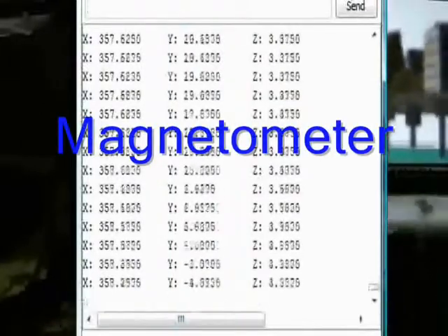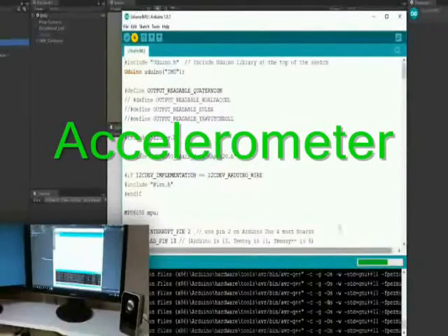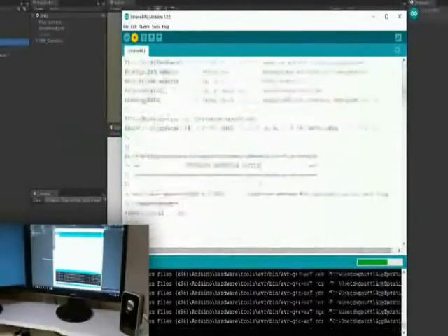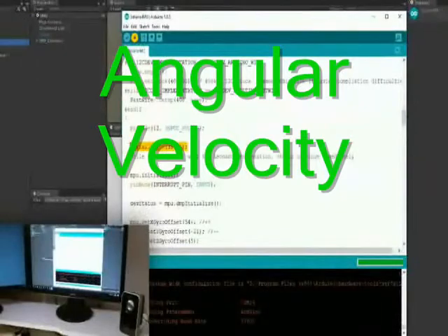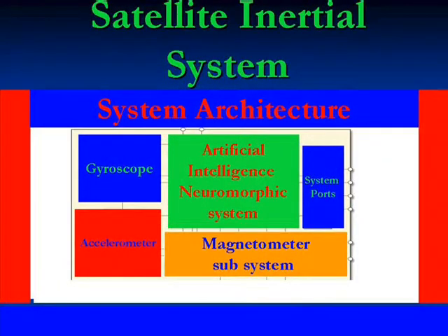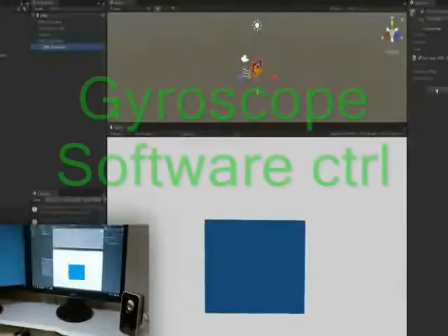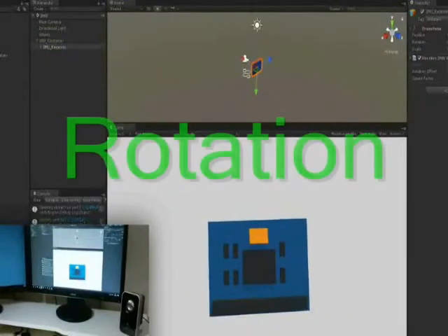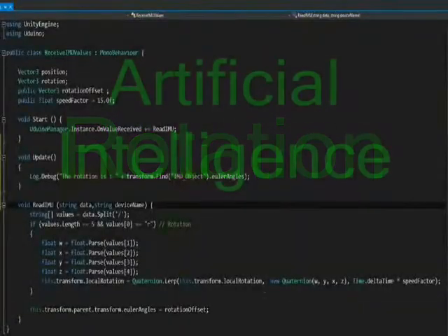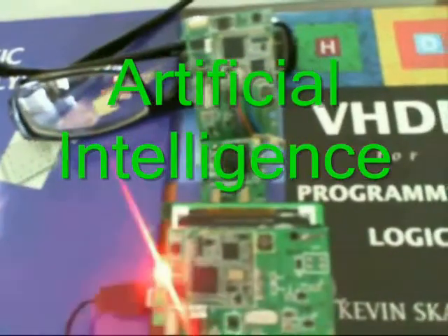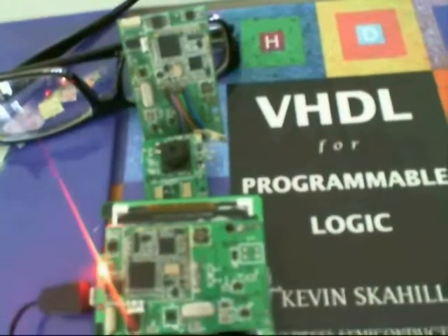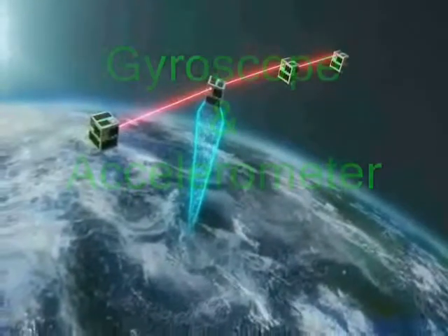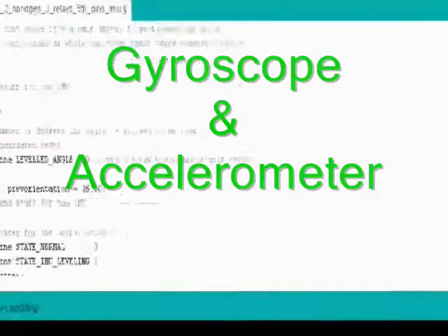The gyroscope is used for measuring and maintaining orientation and also angular velocity. It is a spinning wheel or disc in which the axis of rotation, which is the spin axis, is free to assume any orientation by itself. When rotating, the orientation of the axis is unaffected by tilting or rotation of the mounting, according to the conservation of angular momentum.